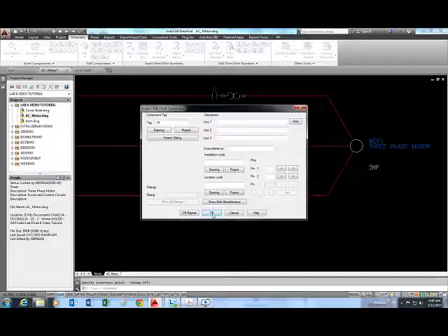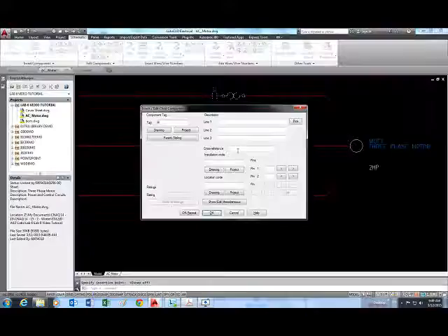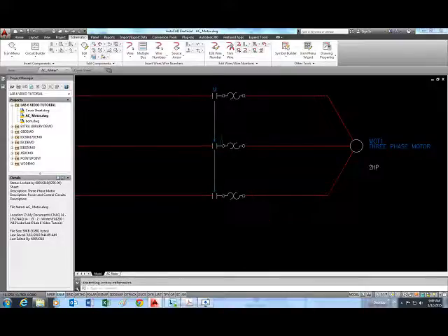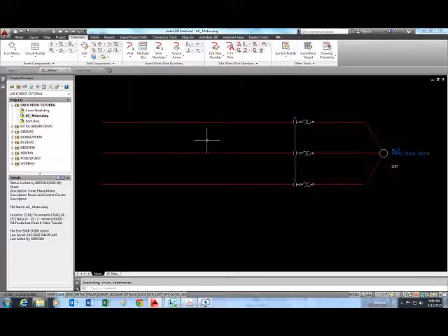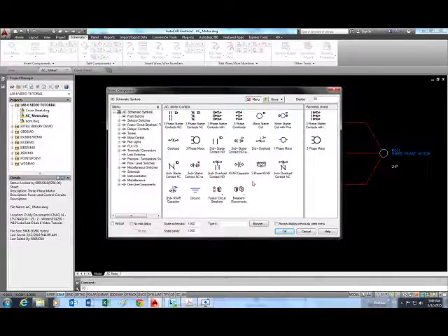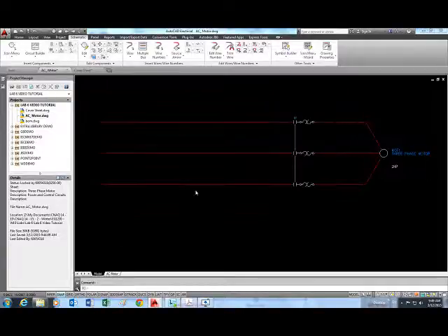And we'll leave this for now as it is. Or you can enter here the same label, motor starter coil. We'll leave it, and we'll do it as part of the parent-sibling relationships, because this is actually physically part of a motor starter, including coil and overload protection. Okay, let's now add the fused disconnects. Let's go motor control, and then breaker disconnects. And there's the 3-pole fuse disconnects.